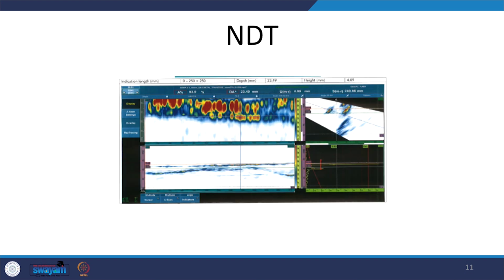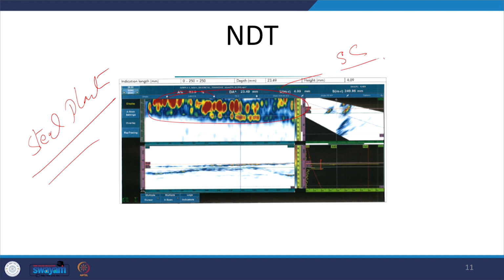Okay. When the steel was subjected to NDT also, to see if there is any issue, the steel plate showed a lot of discontinuities. The steel plate showed defects and discontinuities, and these defects and discontinuities can be zones of stress concentration and weakness, and can easily trigger cracks that then open up during the rolling process.